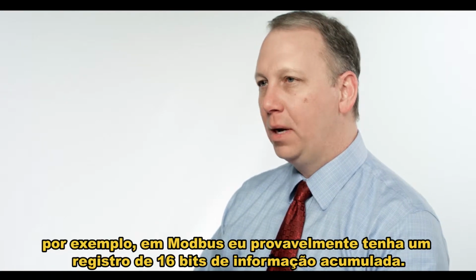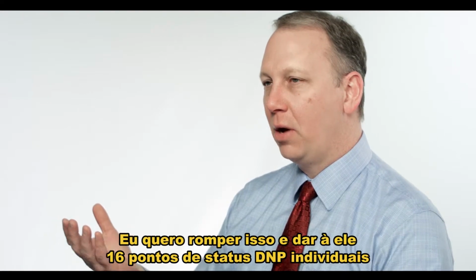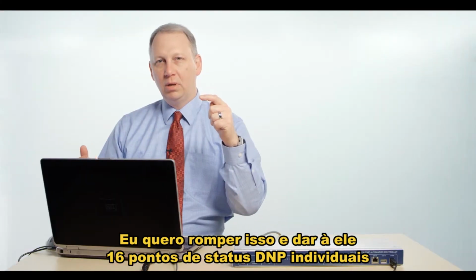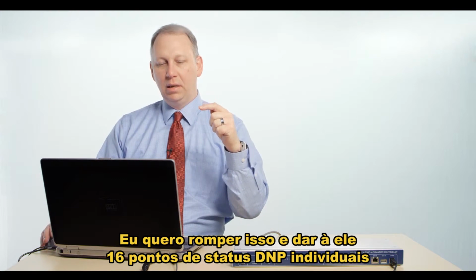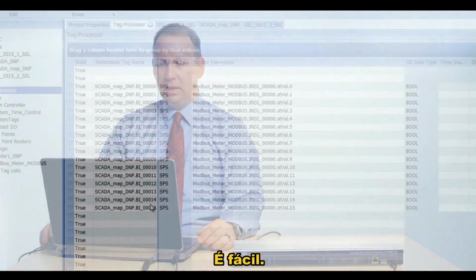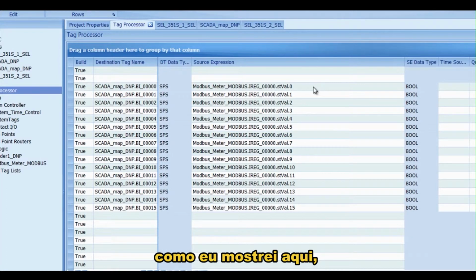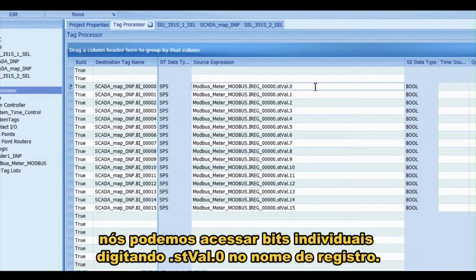For example, in Modbus, I may get a register that has 16 bits of packed information in there, and I want to break that out and give it to individual 16 DNP status points that are going to go back to SCADA. So how do you do that easily? Well, you can certainly do that in 61131 logic, but I could do it right here in the tag processor. And as I've shown here, you can access individual bits by typing in the register name .stval.0.